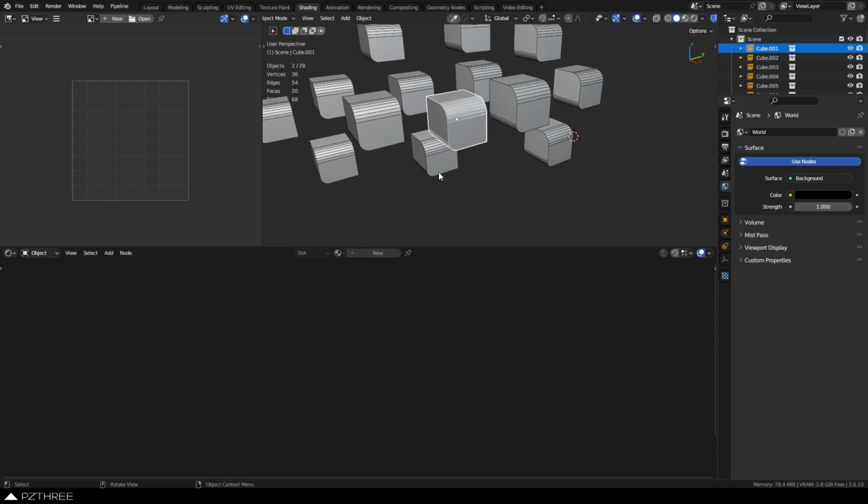But also you can take those base textures that you would make materials out of, and you can blend materials together, and you can use what's called RGB mask, which is still just texture packing. Instead of having grunge maps in the red, green, and blue channel, you have masks in the red, green, and blue channel. And then you can use those to blend on objects.